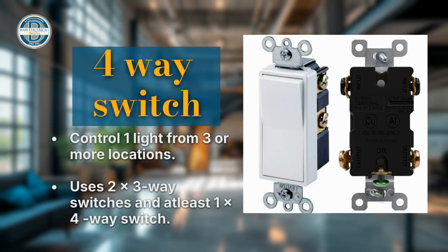A four-way switch setup allows you to control one light from three or more locations. It includes two three-way switches and one or more four-way switches in between.